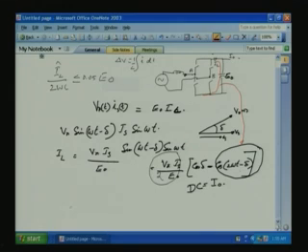The C will be from this inequality: C should be greater than or equal to IL hat, that is the ripple peak, from here, IL hat divided by 2 into 0.05 E0, divided into omega. So, from this equation we can find out the value of C approximately. So, C should be greater than this value.